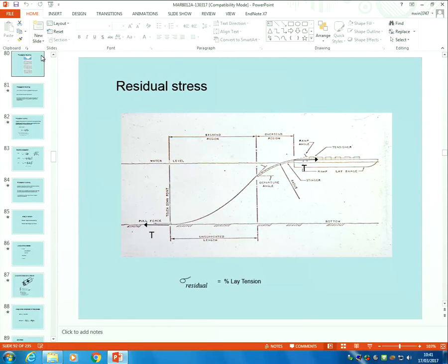So where does this help you with your fatigue? Because when we consider fatigue for the pipeline, the primary stress is actually hoop stress. So I'm just curious, if I need to consider fatigue for the subsea pipeline, when I calculate the hoop stress, do I need to use the thin wall pipeline calculation or the thick wall pipeline calculation? Well, does that depend on what the wall thickness of your pipe is relative to its actual diameter? Is a normal thin wall pipeline less than what that? It's greater than 20. Yeah. Normal pipeline. Yeah.